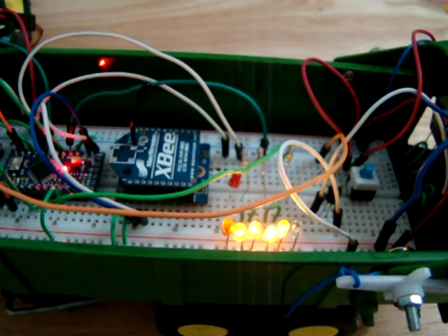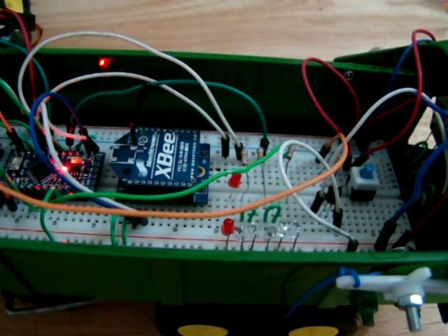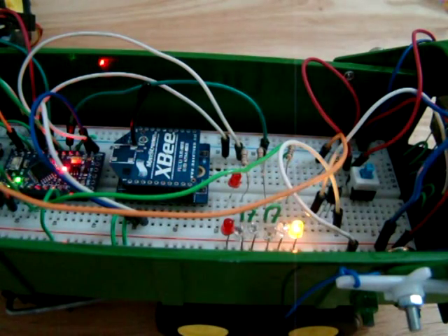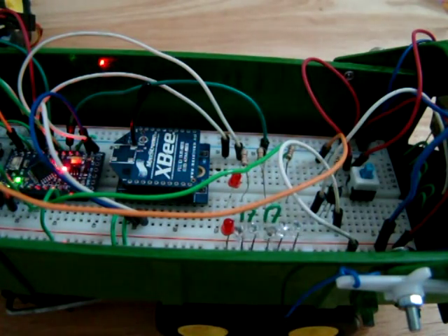So there you go, all our indicators are now flashing, that's perfect. Send it again, turn it off. Okay, and our beacon is 0B. So send 0B, and here's our beacon flashing here. You can obviously change the timing of any of these indicators or beacons yourself in the code just by adjusting the delay times.